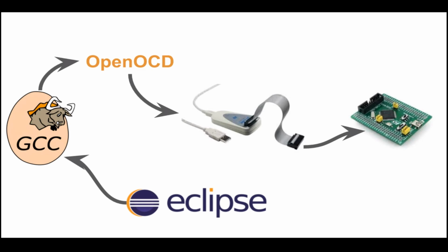And what is this OpenOCD? OpenOCD stands for Open On-Chip Debugger. It's nothing more than a debugger that you use in the IDE. And the really cool thing about this is it can break on the program that executes in the chip. So you can debug what's happening in the IC microcontroller.